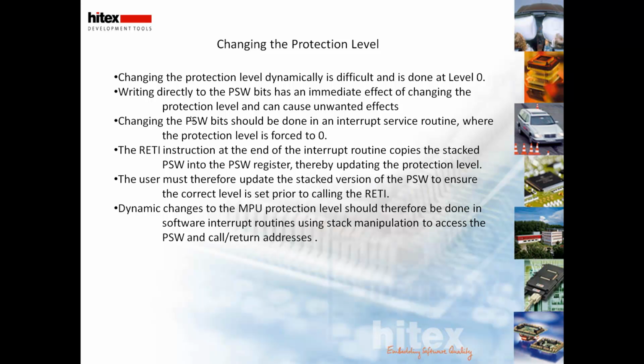Changing the PSW bits should be done in an interrupt service routine where the protection level is forced to 0. In my application example, the PSW bits are managed via a software interrupt, because with a software interrupt, as with all interrupts on the device, the protection level is immediately forced down to 0. If the protection level is forced to 0, then we can change the PSW bits at that level.